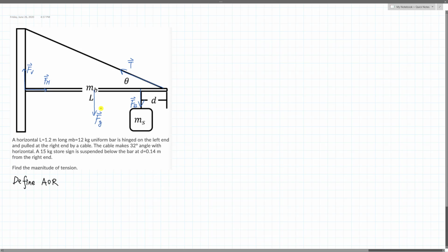Gravity. So there are 1, 2, 3, 4, 5 forces. So the choice of axis of rotation should minimize unknown force torques. I'll have a few choices here. Here's A. Here's B. And here's C. Here's D. So 4 different choices. Let's see. If I choose A, these two forces originate from A, so they will not have any lever arm. And so I'll have 3 forces with lever arm. This is an unknown force with a lever arm, so it's not too bad to choose A.